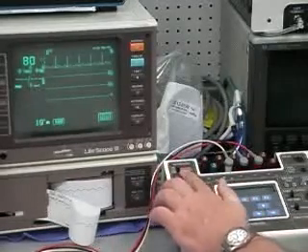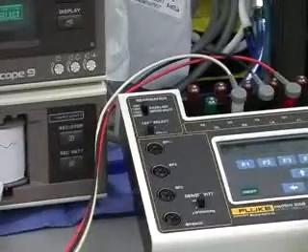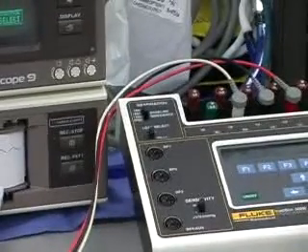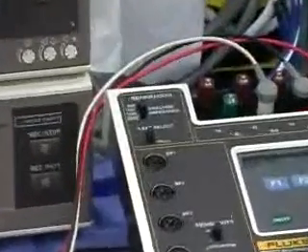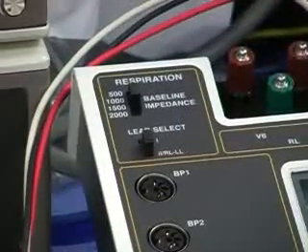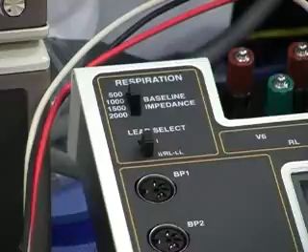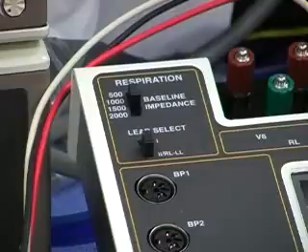Primarily, you're looking at something where you can set the baseline or the patient's chest resistance, typically 500 for the babies and 1,000 for the adults. Some of the higher ones you're looking at for either very obese or geriatric patients with very dry skin on the electrodes. So this could be a good test also if you're looking at testing the ability of the monitor to work with different electrode conditions.